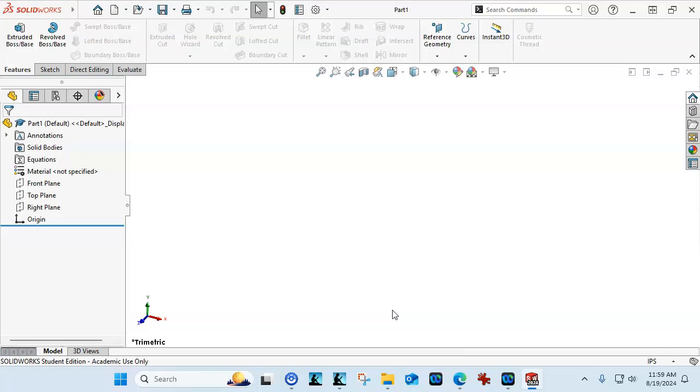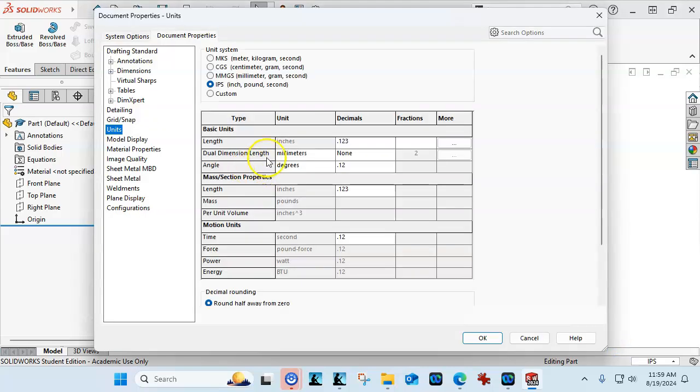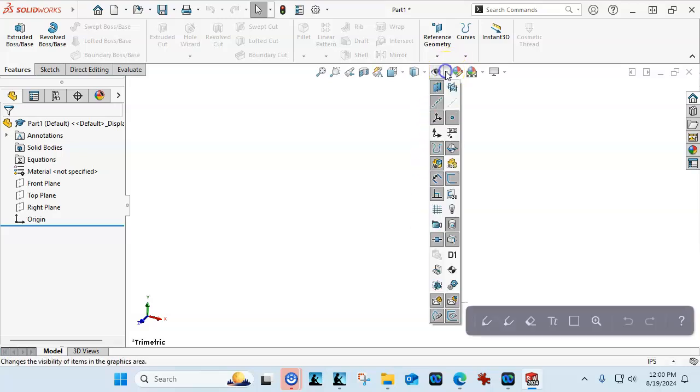We see the command manager pop up. We have pretty much everything we need, but there's a few things that I'd like to check. So if I come down to the units, and first thing, that's my capture software is in the way, I'm going to make sure that my unit, so this template has inches, 3 decimal places, and if we're going to do duplicate, I'm going to go ahead and make it 2 decimal places on the millimeters. So that one's pretty good.